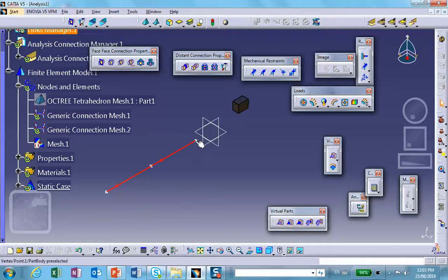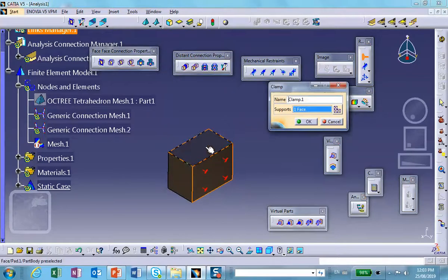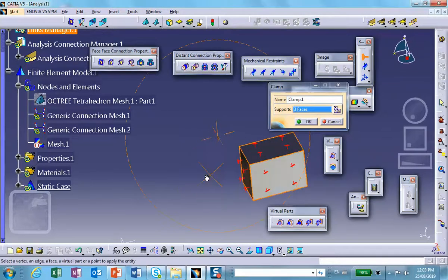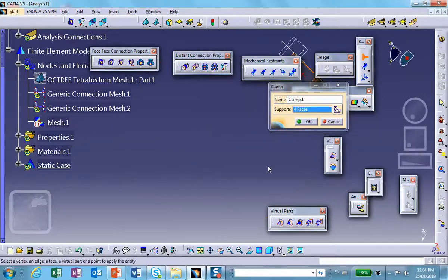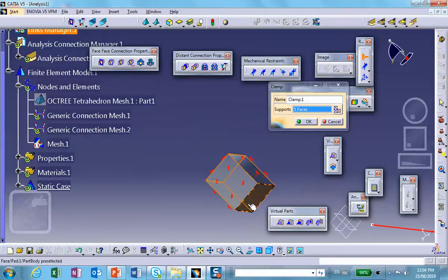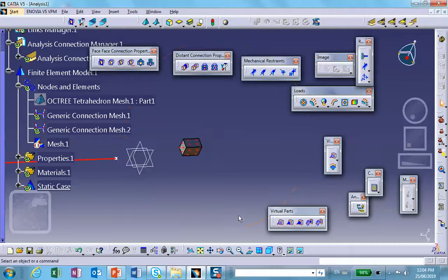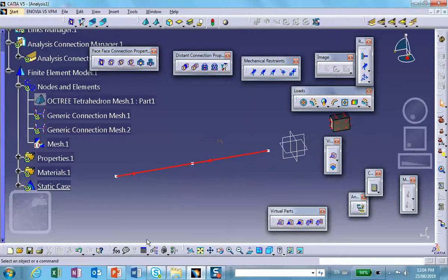So let's actually clamp. The first thing we do is we clamp all the sides of this, because this is not going to participate in my calculation. The only reason I'm doing it is because that's how the modified FEA program needs to be put in there. So this does nothing. It just sits there. What is required in order to do that lump system. Now, this end is clamped. Okay, so let's see that. Clamped. This is the wall. There we are.